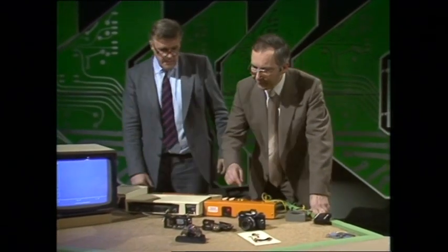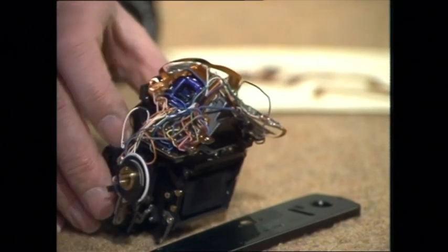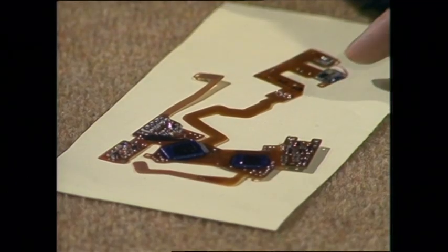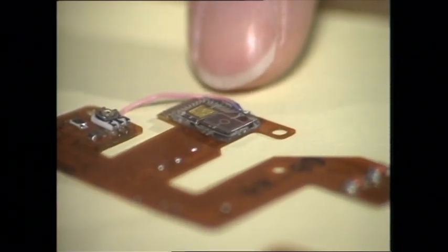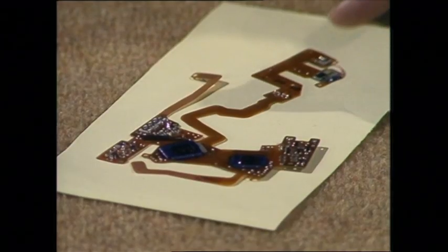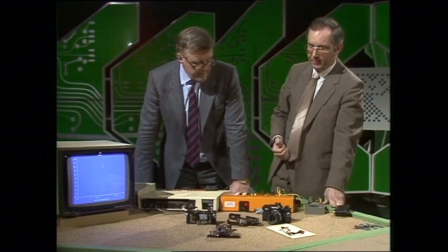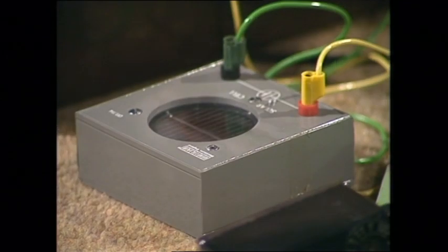Inside a camera, there are a number of sensors, and as you can see, we've taken this one to pieces, and there is a lot of electronic circuitry in it. There's one printed circuit sheet there, which we've spread out here, and there is a photo sensor, which senses the light after the shutter has opened. That's connected to a high-speed analog-to-digital converter, and then through a microcomputer on this flexible board. Once the shutter's open, the camera decides how long an exposure it needs and then shuts the shutter at an appropriate moment.